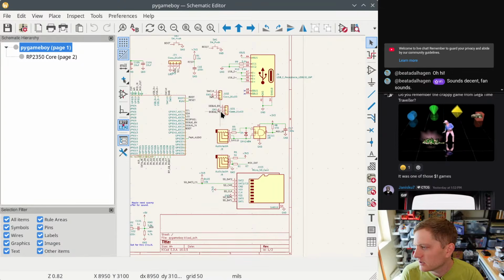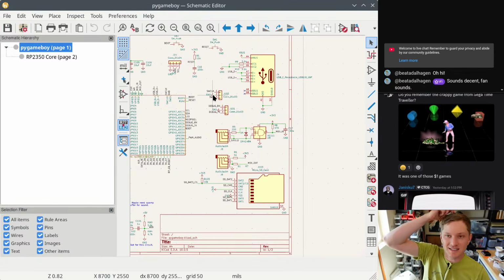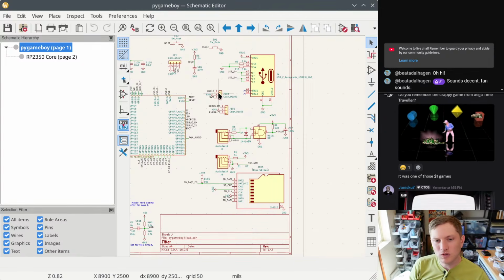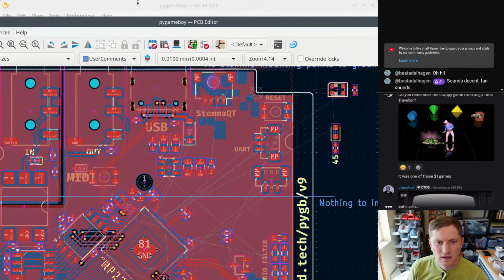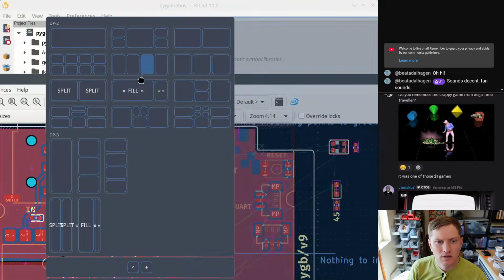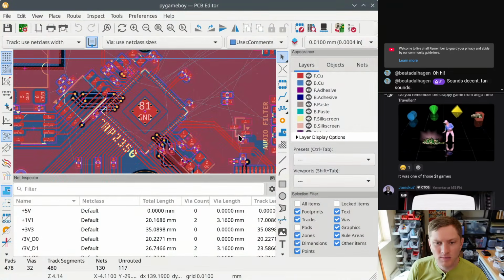I had added debug UART, but I also added debug SWD. Lady Ada's point was that LLMs are actually getting decent at doing debugging using GDB, so you probably do want an SWD connection. The Raspberry Pi folks have set up this 3-pin standard for SWD, so I just threw one of those on there as well. So that's where I'm at. I haven't gotten it to the point where I can order it yet, but I will show you where I am at with the cart.